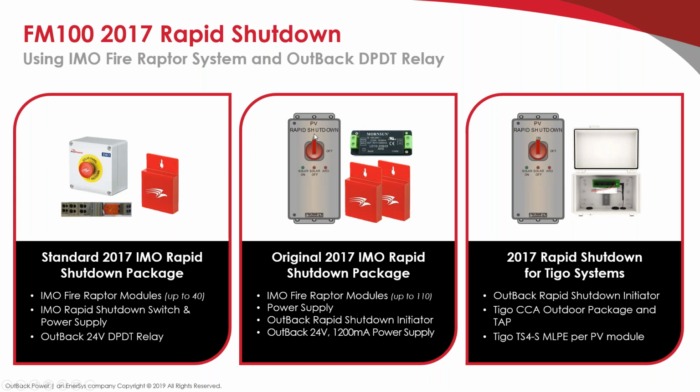If you need more than that, so if you need more than 2 charge controllers, up to 10, this system in the middle here for each power supply can handle up to 110 modules. So that's at least 5, if not 6 or 7 FLEXmax 100s, depending on your string configuration, which is going to cover 99% of FLEXmax 100 installations.